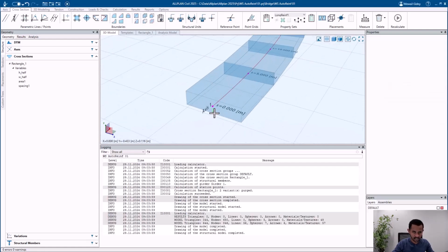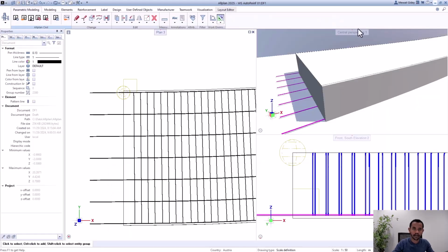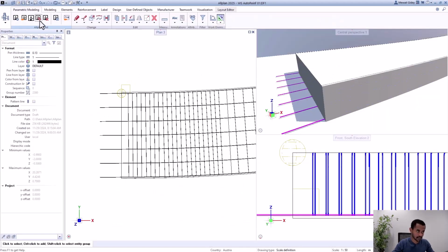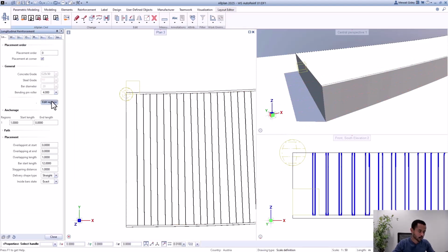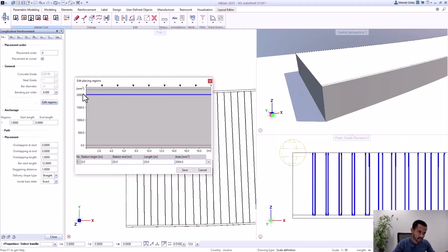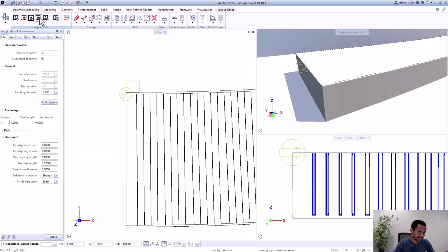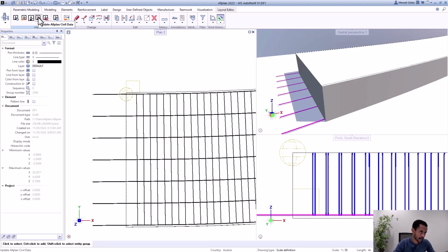It's recalculated. You can see we have everything set up properly here. Come back here, I could just update it there. So if I update it here, normally the longitudinal bars, the area or whatever I set up for the longitudinal bars here would still be here. The area, just remember, it is set up at 20, but the area which is set up by the engineer is at 22. So this would also be kept if I just click update. Other settings also for the overlap, for the bar lengths and so on, they would also be still kept if I just set up the update.